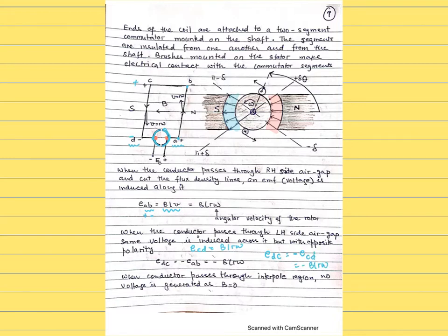So here there's a little explanation of how we do these voltages. So let's say here are the two points. This is the point A, which is at 8 volt. This is the point B, which is at 6 volt. Now, if I want to write E A to B, that means it's 8 minus 6, 2 volt. If I want to write E B to A, that is basically 6 minus 8, which is negative 2 volts. So this shows that A is at a higher voltage than B. The first letter, which is used as a subscript, is always at a higher potential with respect to the second letter, which is used as a subscript.